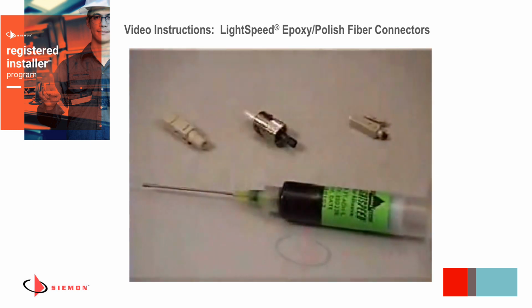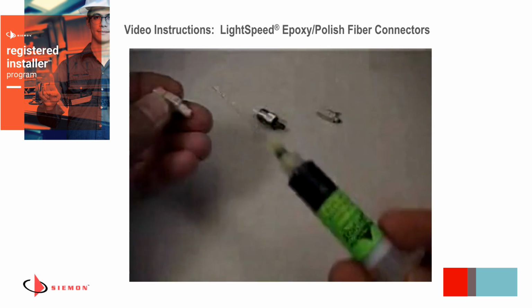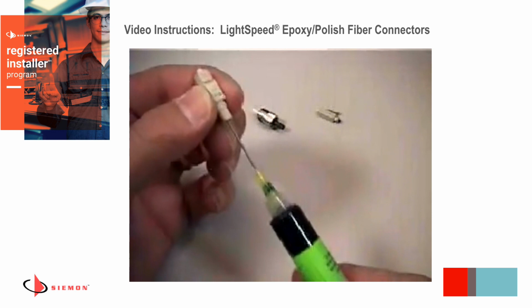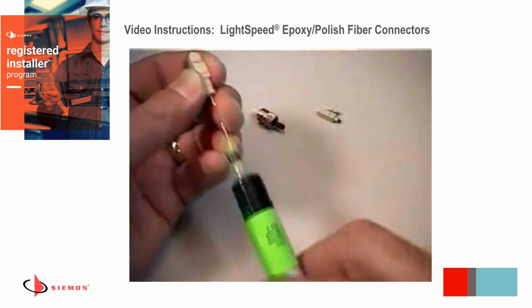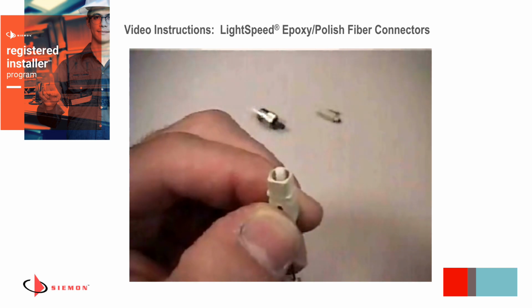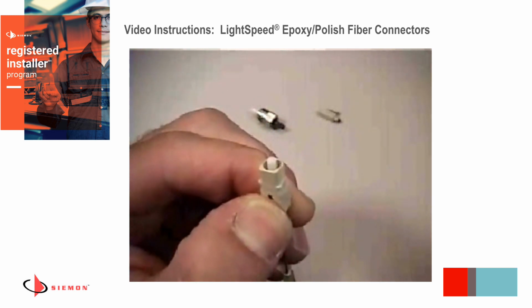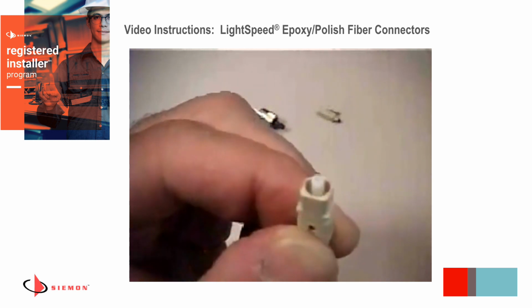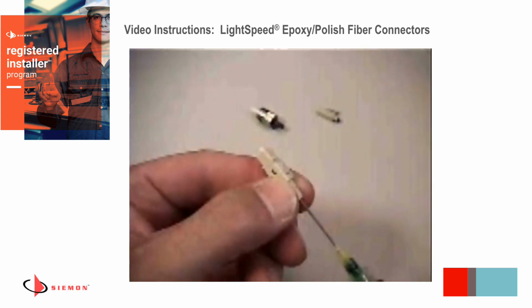The buffered style termination is identical for the SC, ST, or LC connector styles. First, remove the dust cap from the connector and insert the adhesive syringe tip into the connector housing until it seats firmly inside. Inject the Lightspeed adhesive until a small dot of the adhesive appears at the ferrule tip.